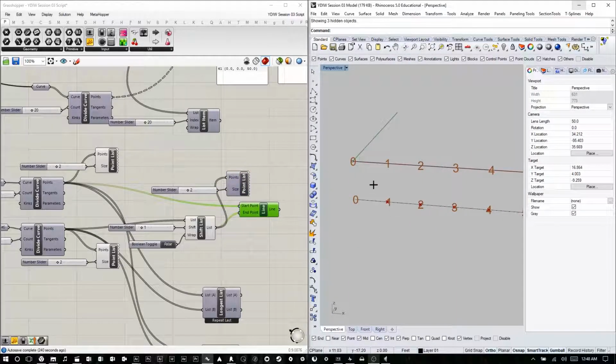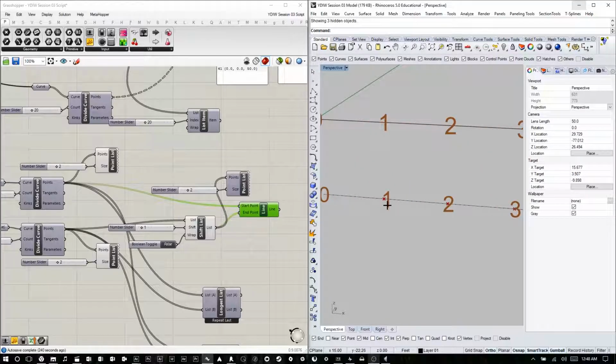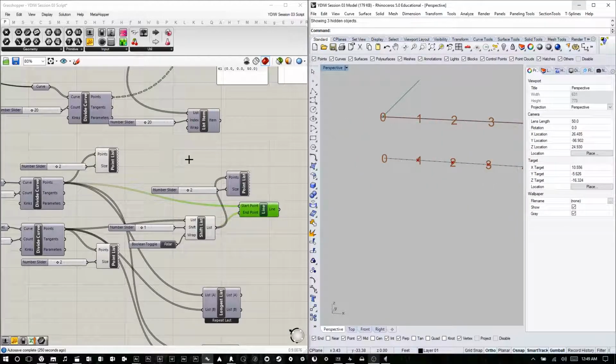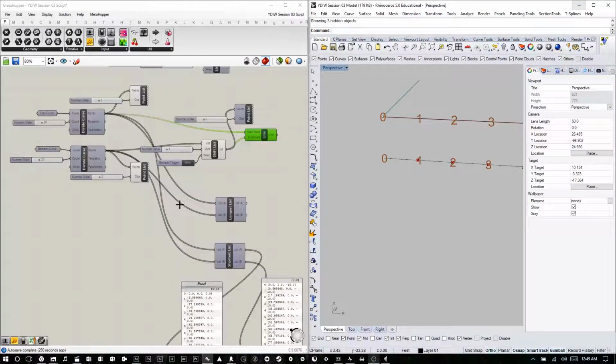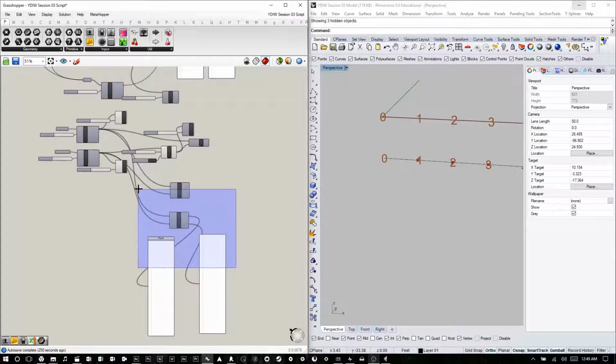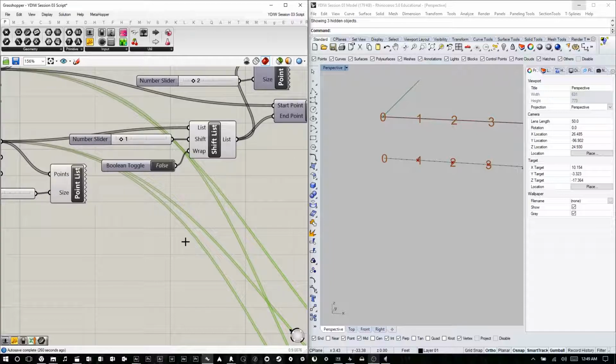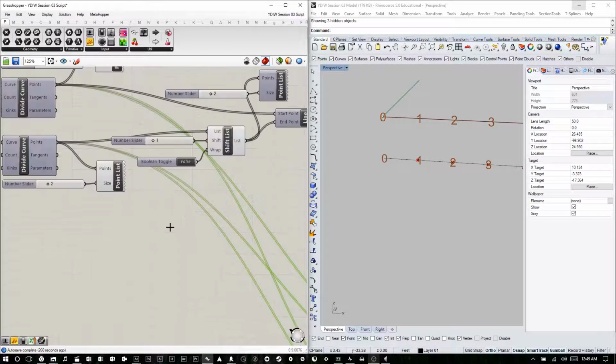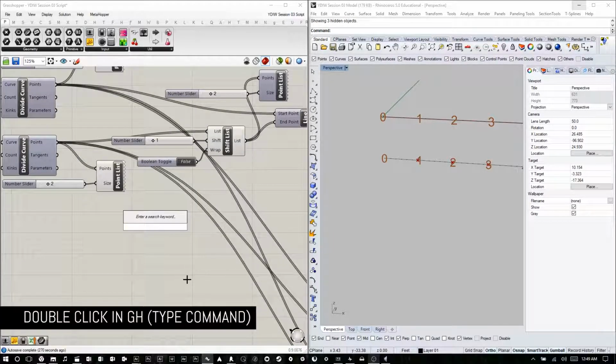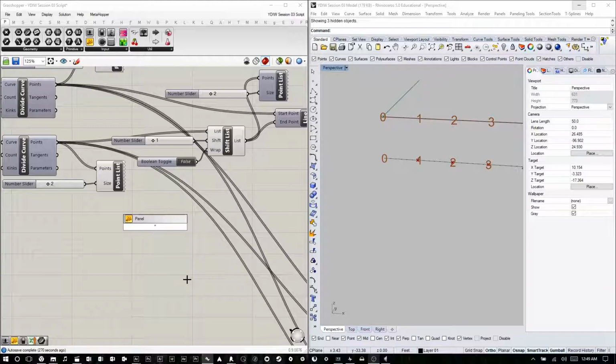What if you want to connect 0 to 1 and 1 to 2 and 2 to 3, etc.? So what you would do is use what's called a true-false dispatch to create a pattern that Grasshopper can replicate through the script. So let's go ahead and create that. So I'm going to create a panel, and a shortcut for panel is quotation.